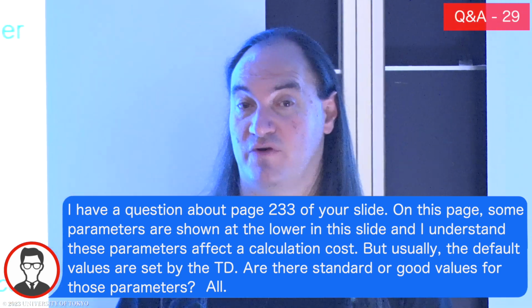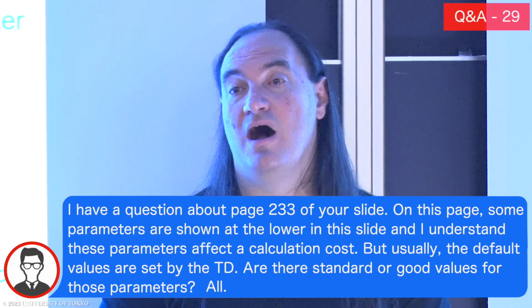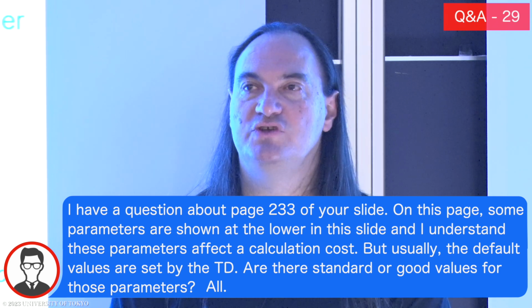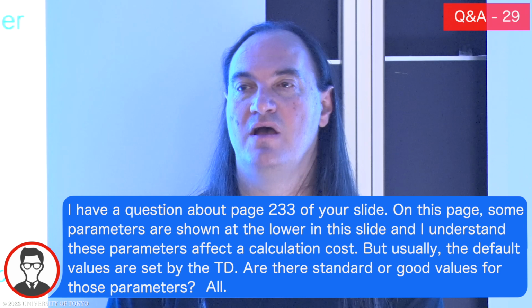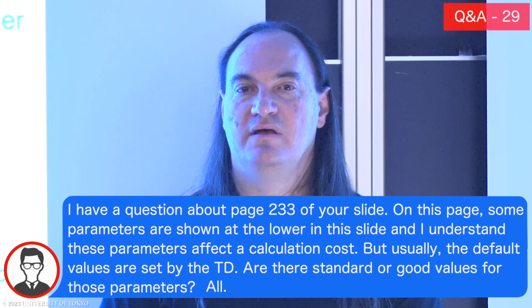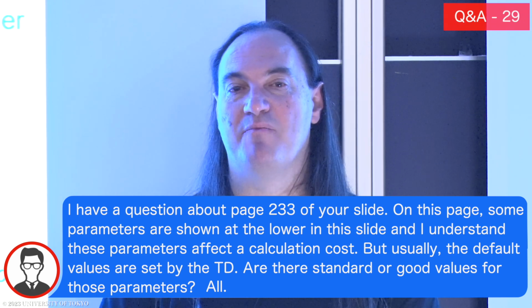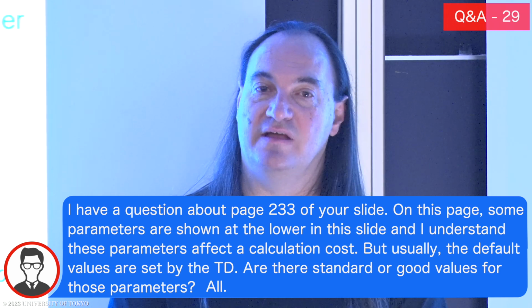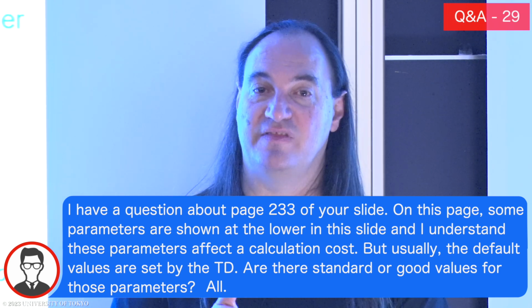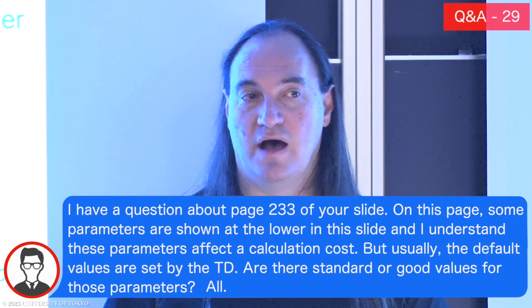For the DTM-PCA, usually I let those stay with whatever the defaults are, but there may be times where I want to say that the stability needs to be better. So if I have something that can't change by more than a degree over 30 seconds, then I would certainly set the DTM-PCA to something less than a degree so that I don't go too far.